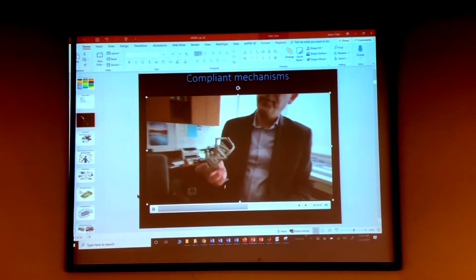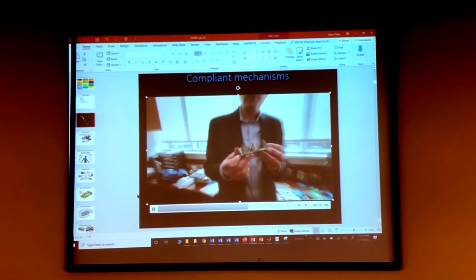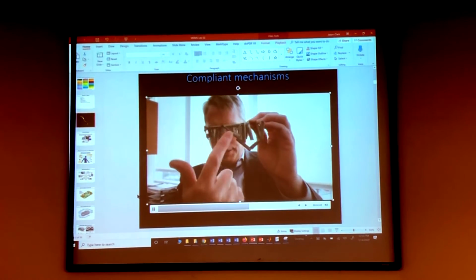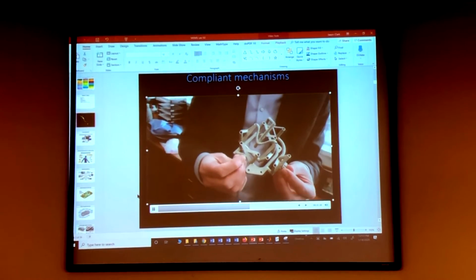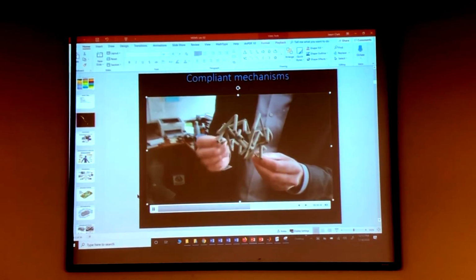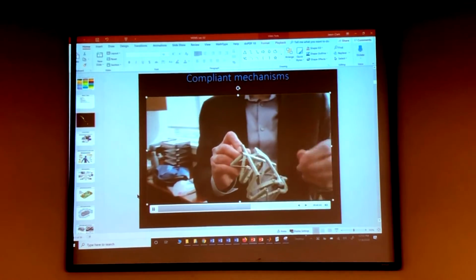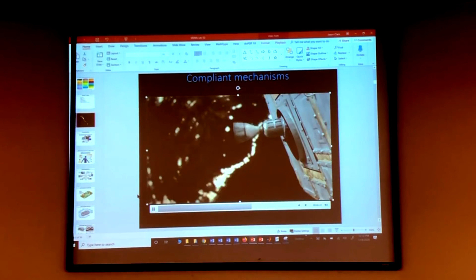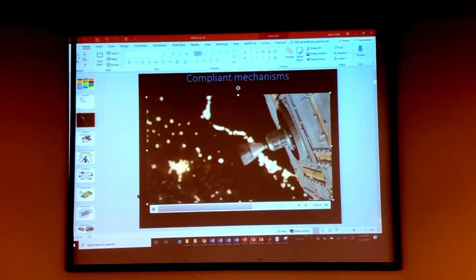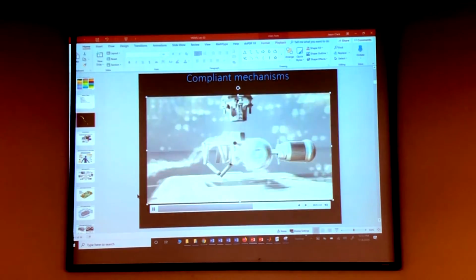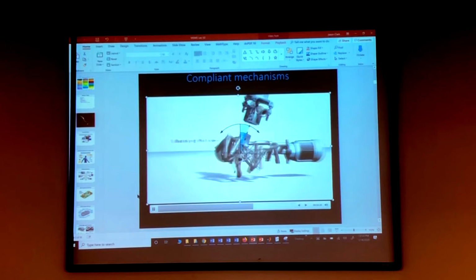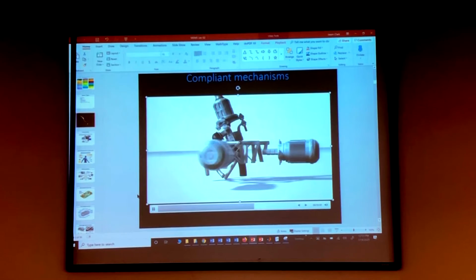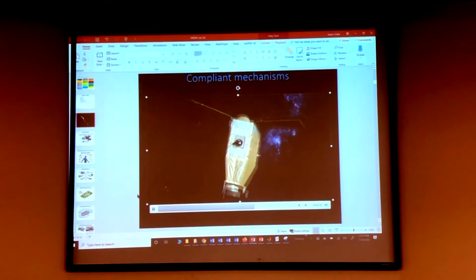this guy right there. So that looks like a crazy beast, but every part in there has a purpose. All these flexible beams, here are the two inputs. And again, we did this with NASA for thruster application, where you can put a thruster right there. And now, with our two motor inputs, we can direct that thruster in any direction. That titanium device moves that, and you notice that it's just all bending. It's all solid state too. And there's no pinch points for the fuel lines or electrical lines coming in. Here, this single piece of titanium allows you to use one thruster in place of two.